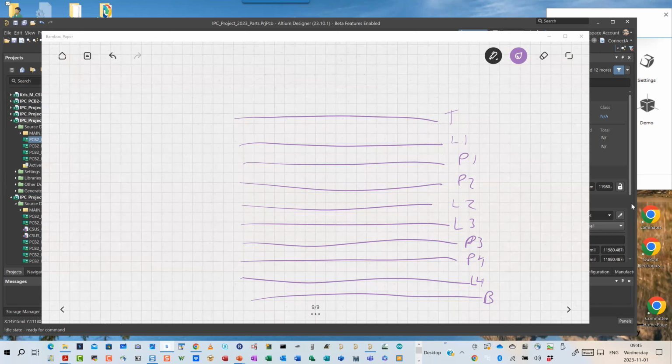9 layers. This is an older version where I didn't do the symmetry on it. If you come back and take my advanced design concepts class, you'll see the non-symmetrical structure in this design is actually okay because that last layer is A, very thin, B, does not have reinforcement, and is only used for the laser microVia layers. So we actually can get away with it, but yes, it should be the 10 just to be symmetrical for the purpose of this class. So yeah, this one probably is missing a routing layer. Great question, Kevin.